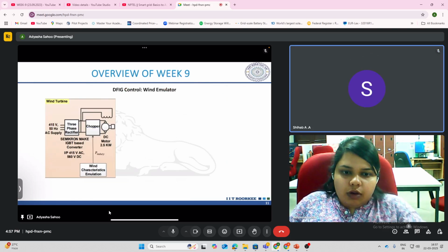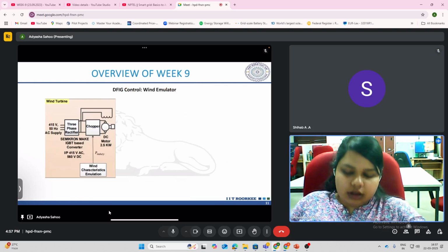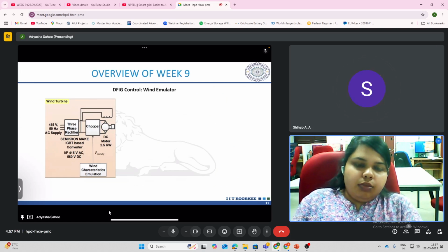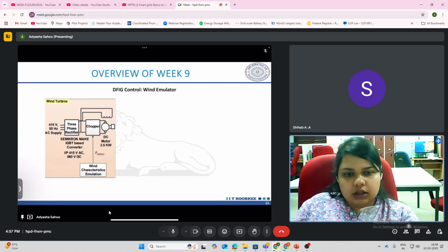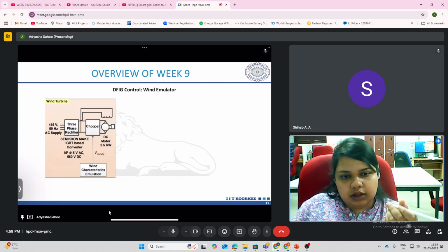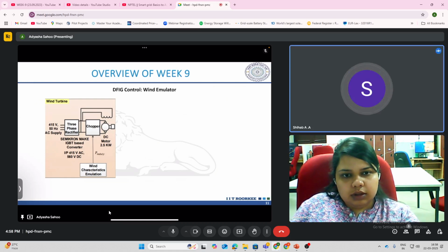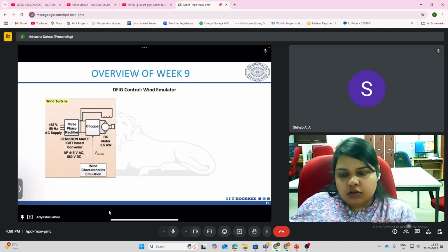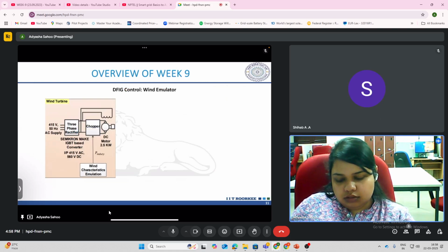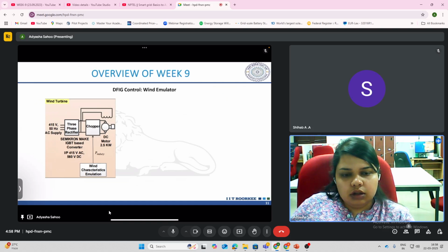So, to perform the experiment in the lab setup, like for the PV panel where we used a programmable DC source, instead of the physical blades of the turbine and the gearbox, we are using a motor to rotate the shaft of the generator instead of the wind. So we can control the speed of the DC motor to have different wind speed levels or different characteristics of the wind.